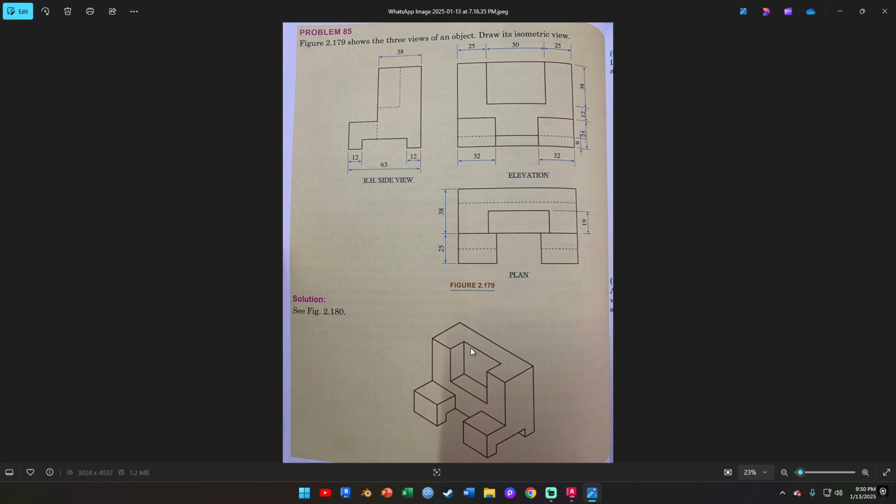You have an indent into this object. Similarly, you also have another hidden detail here, which is this leg being blocked by the other leg from the side. So that's basically it for the end view, or we can also call it the side view.